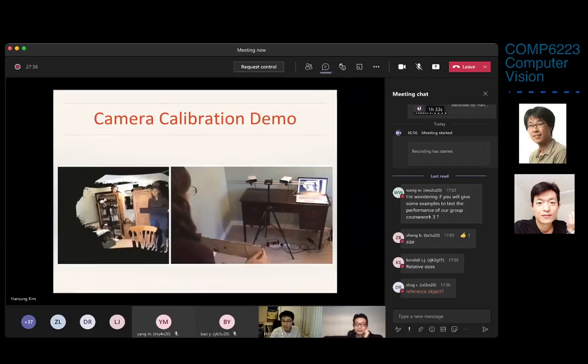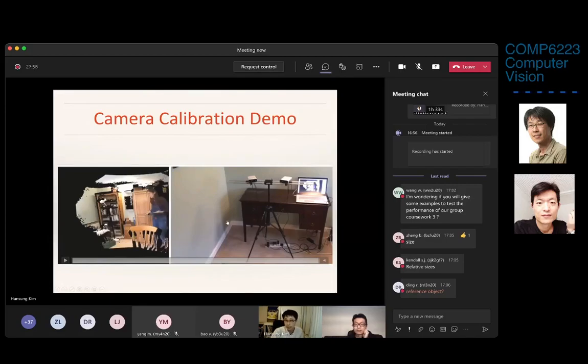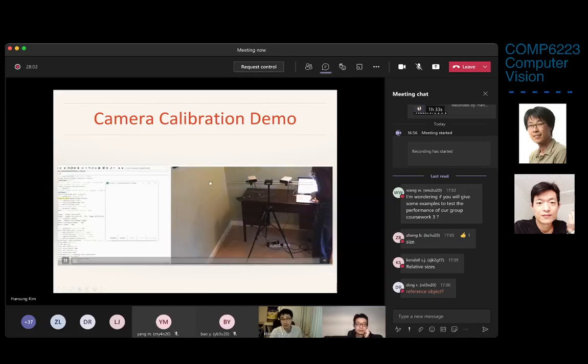Yeah, should be done. Now you can see that. Now you can just see one image. Actually, this is the registration of two video streams together into one, with all the depth and texture from four cameras. They are now registered like that after extrinsic calibration, because they are registered into the same world coordinate. This is the process of camera calibration, just an example of that.